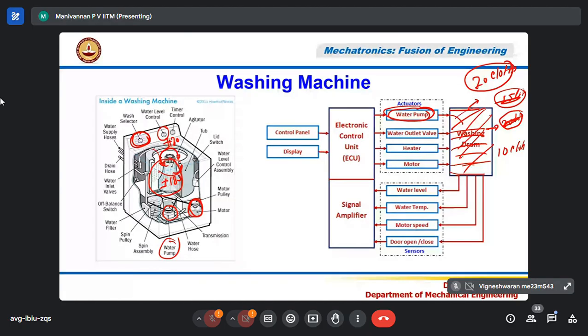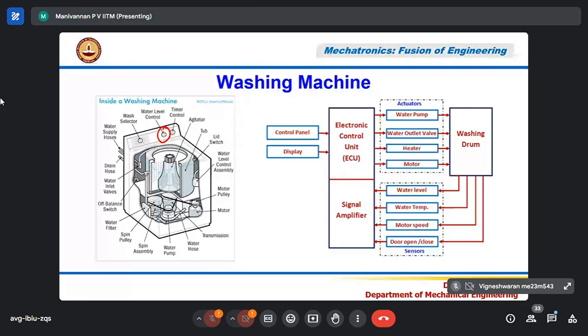It is a waste of an expensive and rare commodity nowadays worldwide. Correct? Clean water. So that means I don't want to fill my drum with 15 liters to wash. I fill 7.5 liters, and that drum is sufficient. We select the water level. Correct? I can say half tank only, because in my machine I have 5 levels. Correct?